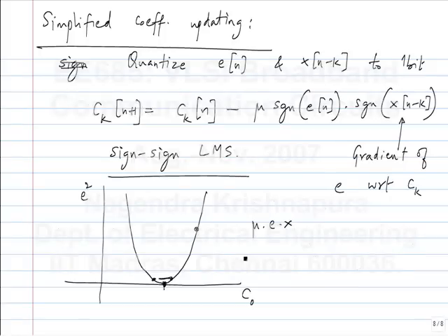Yeah, that's possible. In fact it's quite common in adaptation, because initially you want a crude, fast adaptation, so you use a large value of mu, and as you get closer you use a small value of mu so that adaptation noise is small. This is known as adaptation noise. In this kind of thing, the coefficient finally will not settle to a constant value in any case because of noise and other things. So that is the other reason why you have to make the value of mu sufficiently small. First of all, of course, it has to converge, that's a basic thing. But then, from one step to the next, in this particular simple case, it looks like it can go to 0 and sit there. But in case of an equalizer, it may not be able to do that.